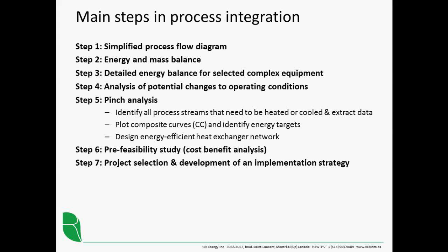And it's really key that we do this analysis of potential changes to operating conditions before we look at heat recovery potential, because if we make these changes to operating conditions and they improve the energy efficiency of different parts of the plant, then that will consequently limit heat recovery opportunities from those parts of the plant. So we have to consider those first and take those into account before we count on using the heat, recovering the heat from those parts of the plant. Because if our plan is based on recovering heat that then is no longer available because of an operational change, it's a pretty poor plan.